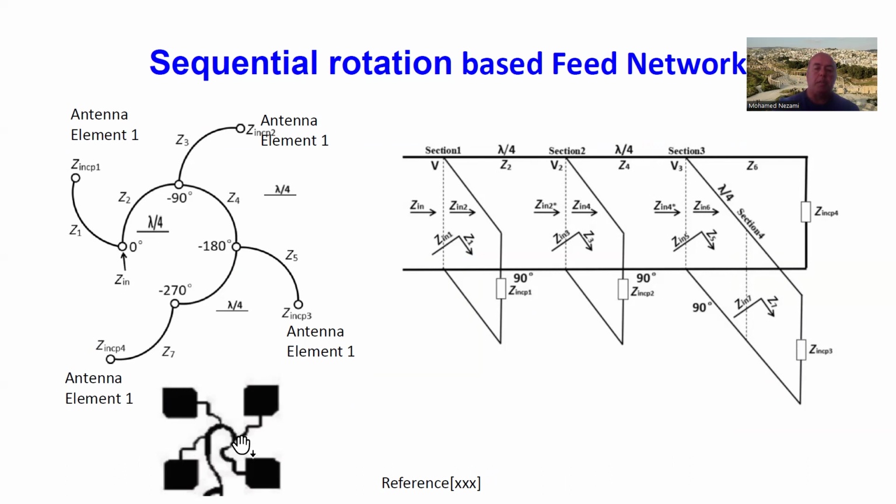So what this really is, is 3 T-splitters that are circularly placed in a pattern so that the signal flows according to this scheme. We feed the signal in here, and we put the first antenna here. That's one quadrant. We have a quarter wave transformer, and then feed the next, second antenna. Then another quarter wave, and we feed the third one, another quarter wave microstrip line, and then we feed the last one. Of course, these lines are all the same length, in theory.